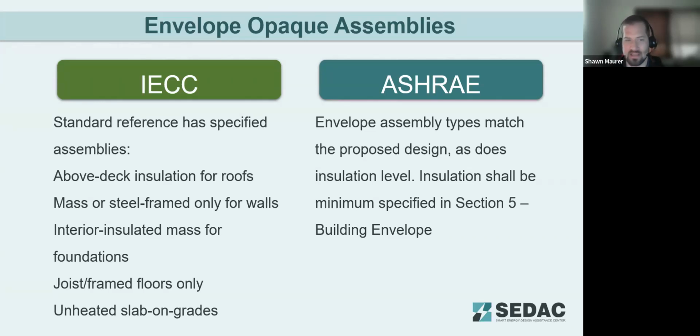Similarly for foundation requirement, just as another example, since the IECC requires interior only insulation, it removes the ability for the model to project the impacts of that thermal mass, where with ASHRAE, if you're using exterior insulation, both models would have exterior insulation on them. And so with the IECC, you get a little bit more benefit if your proposed model has that thermal mass within the insulation layer, where with ASHRAE, again, you've got that more direct comparison between your two building designs.